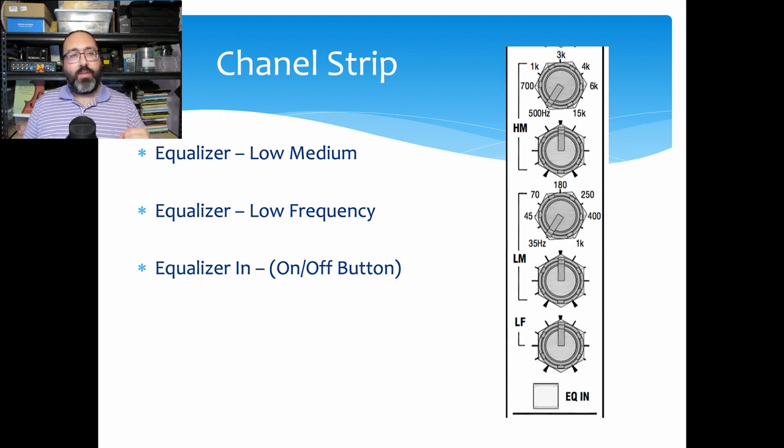Now, something very important about this console or any console, if you're trying to use the equalizer, you need to make sure you use the equalizer in. I don't know how many times I've seen somebody fiddle with their equalizer knobs, fiddle, fiddle, fiddle, thought they were doing something, and they never actually activated the equalizer. So make sure that if you want to use the equalizer that you do it.